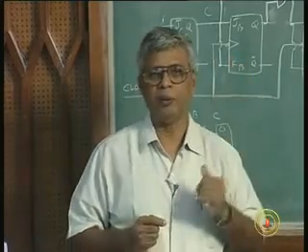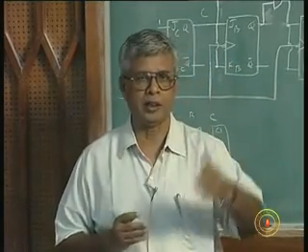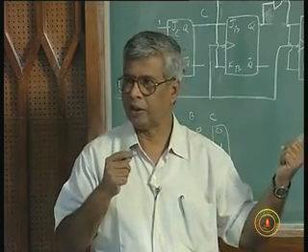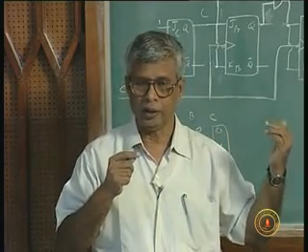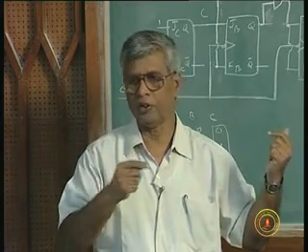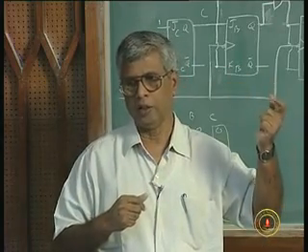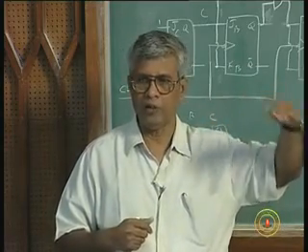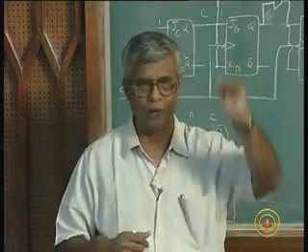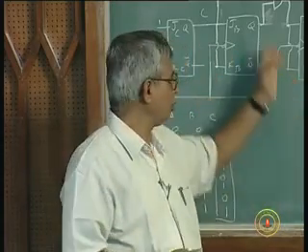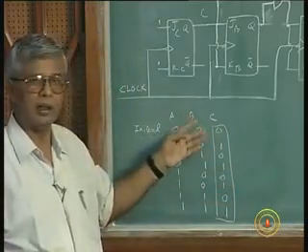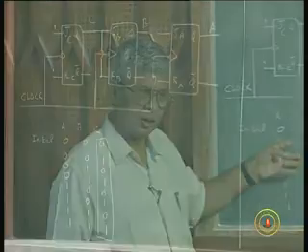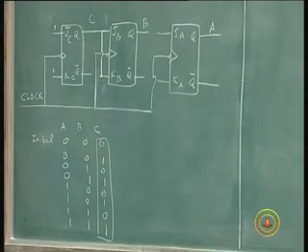The first flip-flop received the input clock, the system clock as they call it. The second flip-flop received a clock which is half the frequency of the first. The third received a clock which is 1/4 the frequency of the first, and so forth. So we divided the clock, used lower and lower frequency clocks, and we were able to get the toggling action slower and slower. The idea is that the first flip-flop has to toggle very fast, the second flip-flop has to toggle at a relatively slower rate, and so forth. Toggling is required but needs to be controlled.